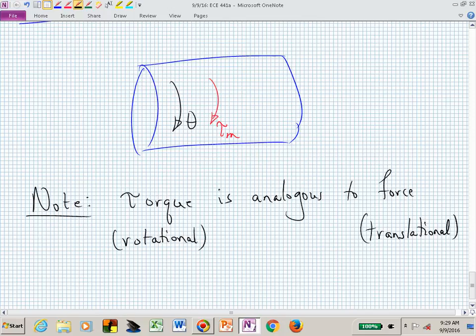It's going to have some inertia that opposes that movement, isn't it? That's our inertial torque, so to be consistent with before, let me call that tau sub I. Let's also say there's some fluid, maybe air, that provides damping proportional to the velocity of the shaft spinning, and that produces a torque we'll call tau sub B.